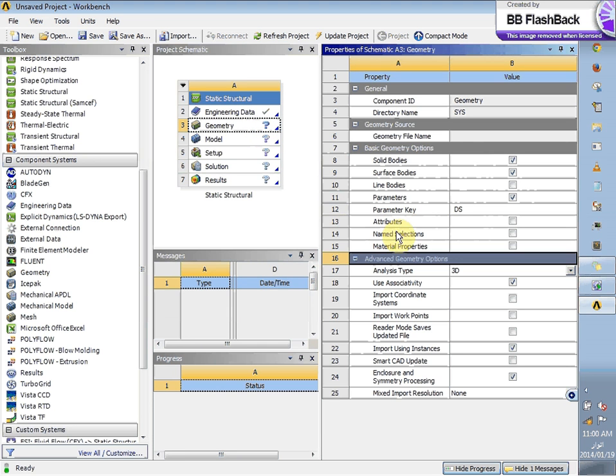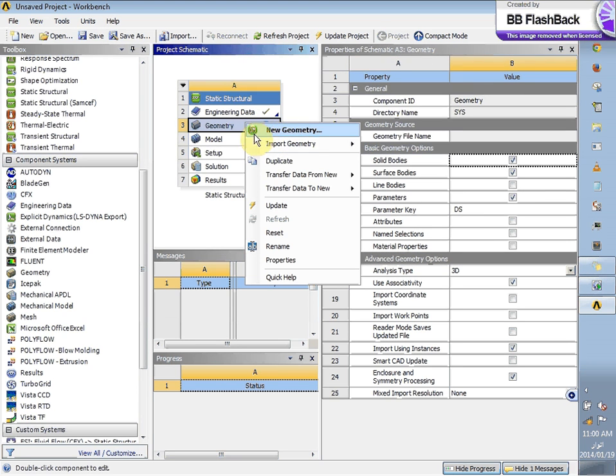Also the material properties do not need to be transferred to the geometry. If you want the material properties to be available in the geometry too, which is not required in fact, but you want to see the difference, that here is the steel and then it is aluminium and other different materials defined separately in the geometry as well, you can check it here and it will show you the difference there. We are not interested in that either, so we are ready to start modeling it. The question mark is telling us that it has not yet been defined, and the filled question mark is telling us this is required to be done now before doing anything else. This is the first thing. So when you right click on it, a menu will appear and it shall tell us to use DesignModeler, another software that comes with Ansys.